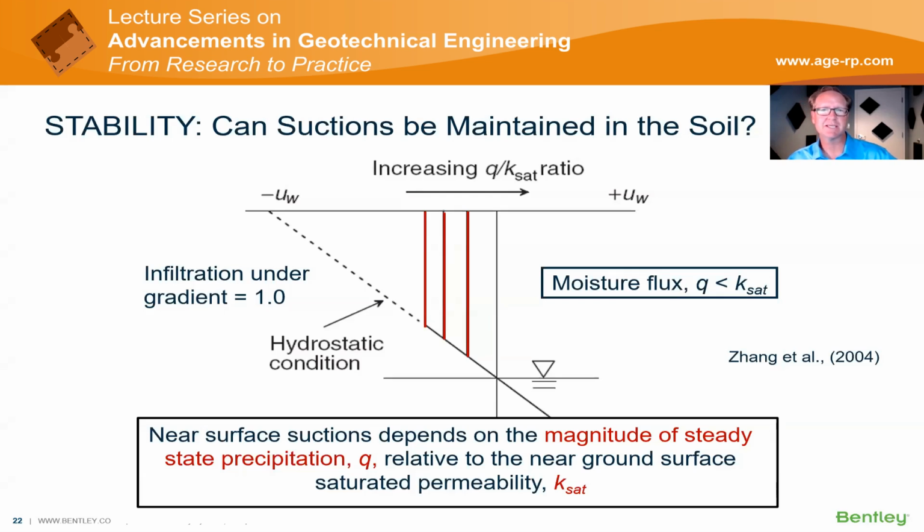What will happen in this case is that if you rain at a rate that is less than the KSAT, you will equilibrate at one of these vertical red lines, where the flow into your model is enough that the flow is being allowed to come in. However, it will continue along this forever, and soil suctions will still be maintained in the soil.